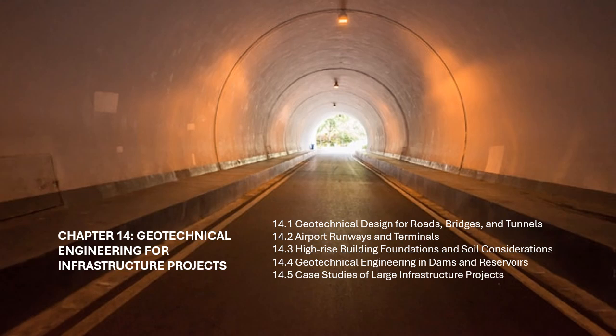High-rise buildings exert significant vertical loads on the soil, which can lead to settlement or differential settlement. Differential settlement may result in structural damage or misalignment of building elements. It is essential to design foundations that minimize settlement, which is achieved by careful evaluation of soil strength, compressibility, and the use of appropriate foundation systems.